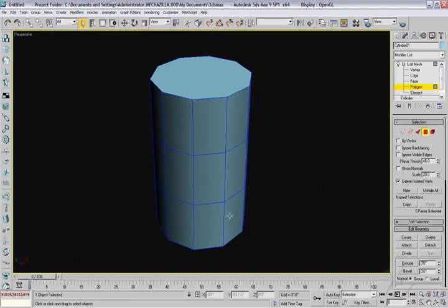In order to do so, we need to hold down the Control key. So click on your Control key and hold it down, and you can single click on one of the vertices, either one. You can also click on that one, either or. What we want to do is select every other one. And with them selected, we're going to navigate down to the viewport tools. I'm still holding down my Control key at this point. And I'm going to click on my Arc Rotate Selected.